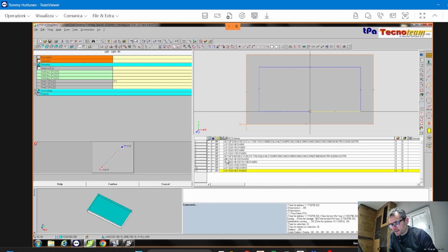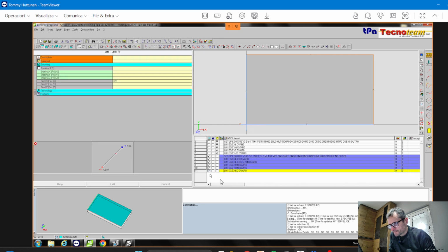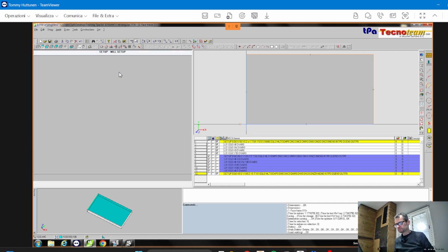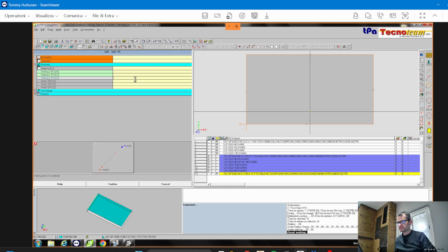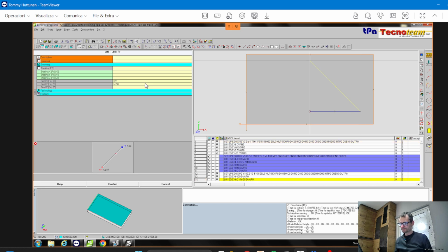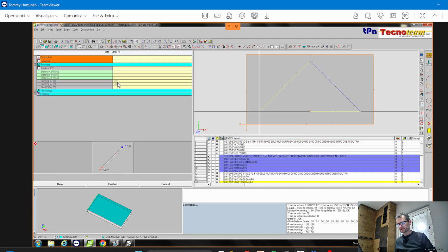Okay, now I want to deactivate it because I want to produce a triangle. To produce a triangle is the same thing. This is the first point, so setup. I put LF divided 2 because I start from this point, 100, and the depth, minus 10. Tool 101. Now I go, for example, endpoint, LF minus 100. But now I need to go with the 2 axes. This point is LF divided 2 in x-axis, and in y it's HF minus 50. So in this situation I have to write 100 and 100. The last segment will be just the x-axis moving in LF divided 2.